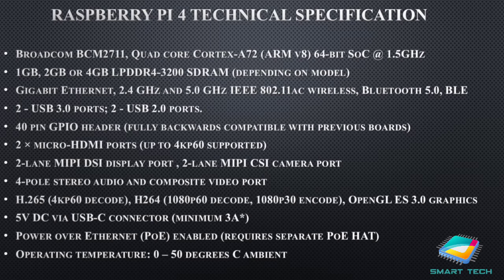It supports a number of encoders like H.265, H.264, OpenGL, etc. It also supports a 5V DC USB-C type connector. Power over Ethernet is also available with this, but for that we require a separate PoE hat. The operating temperature is between 0 to 50 degrees Celsius.